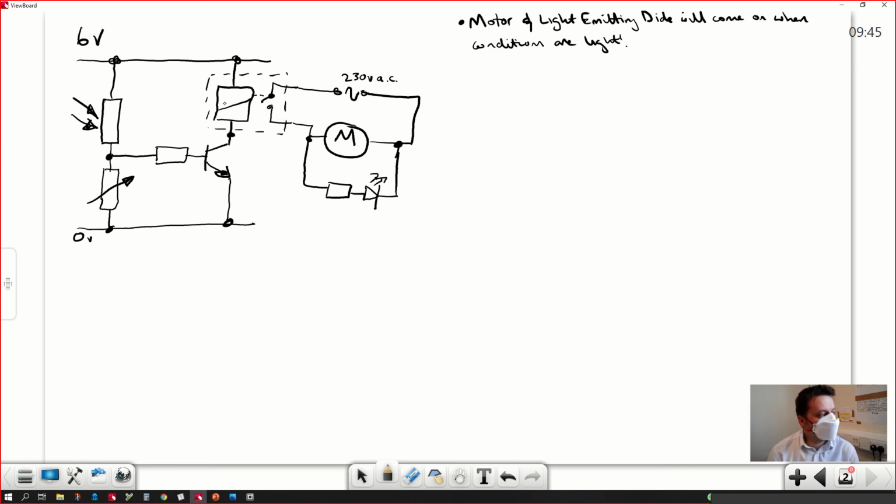That electromagnetic device, when it's powered off, could very well destroy that transistor. So it should have just a normal signal diode in there. So there's a wee component missing from it. If you've got a relay, a motor or a solenoid in that position, you need to put a diode across it. So there's a statement there.